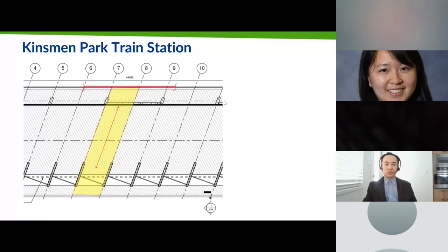And one of the main challenges was laying out the panels. So CLT panels are typically prefabricated in widths of up to 8 feet to 10 feet or so, and in the length direction they can be prefabricated in lengths of up to 40 feet or longer. And so we elected to arrange the panels in this way, as shown in yellow, spanning from north to south. But you can see that each panel is only supported at 3 points, and that doesn't allow for a very good support condition. So what we ended up doing is we introduced a concealed steel member in red along the north edge, as shown by the red line there.